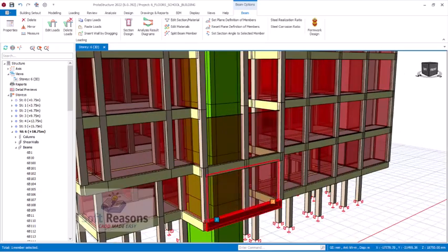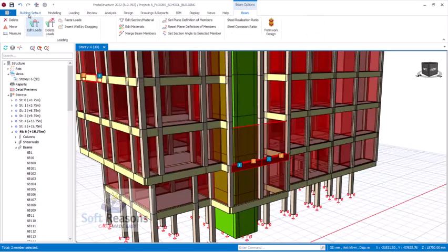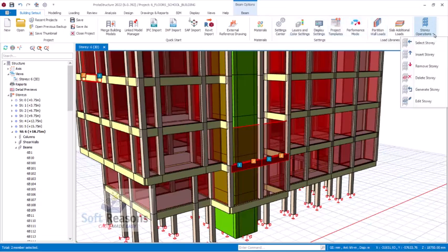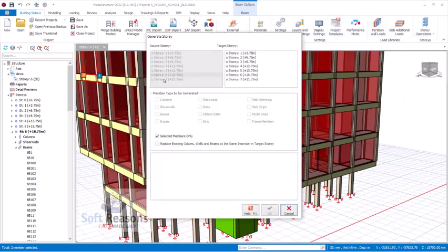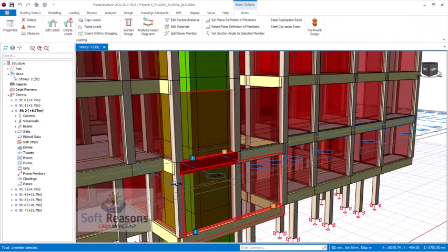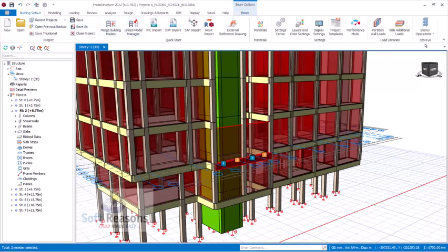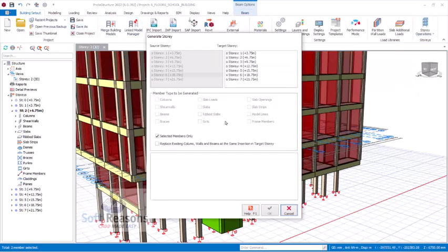Alright, so we make progress. I will select this beam and this one, and then I'll navigate to the set out, and then I'll get to stories, and then I'll generate this. Let's move the grid line to story 2, so that we have that as our source story here. Select here, and then control key, select that. After which you go to the building set out, and then you select and generate stories. So we are to generate this for story 3 and then up to story 7.